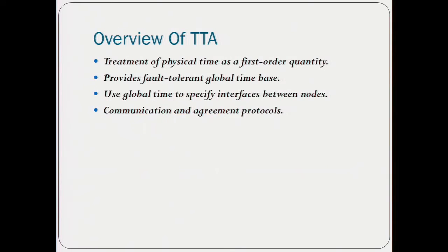Okay. So the treatment of physical time as a first-order quantity is key, as we said. You need to have everybody think the same about time. Now, by the way, it provides a fault-tolerant global time base. Fault-tolerant meaning that even if the clock drifts, I have a way of realigning them. And one such scheme is what I told you. And it uses global time to specify the interfaces to the bus. Because essentially, when time comes, I will need to transfer the data that I computed to the bus.